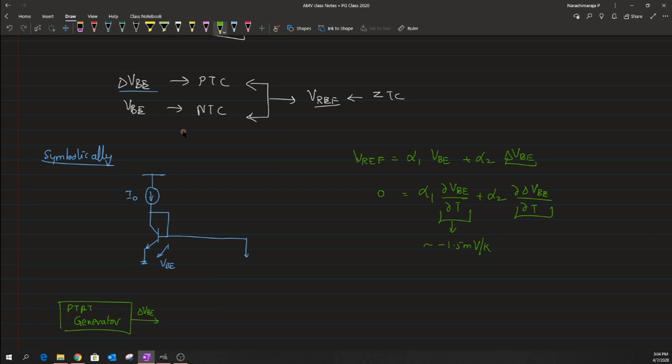So which means that at the same room temperature, when we try to evaluate for an n that is equal to 10, okay, so it is only for that specific value. When we evaluate it, we end up having a factor for this which turns around to be, I think, 0.198 millivolt per Kelvin. So as you can clearly see, towards this end we have this minus 1.5 millivolt per Kelvin that has to be added to this positive term, which right now is not equal to plus 1.5.